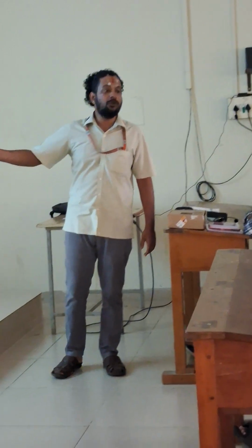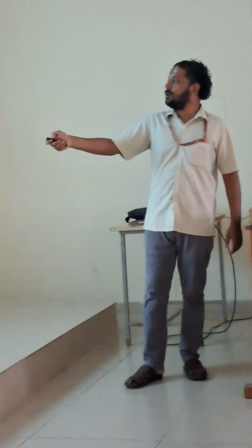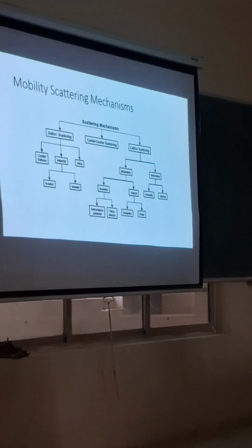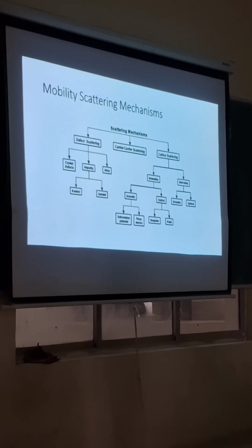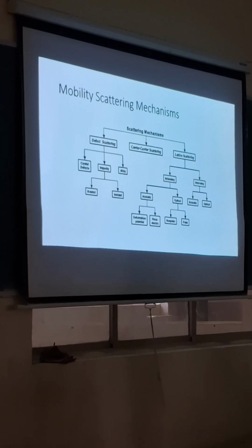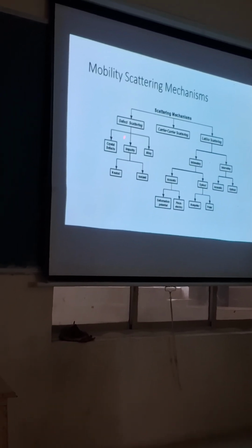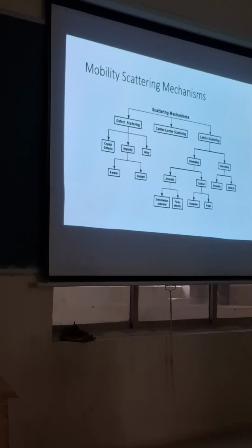And then we have the diffusion process. Higher concentration here, lower concentration here. Balance. So these are the equations for the diffusion process. And these are the different scattering mechanisms that we need to account for. We have the defect scattering, where I have a crystal structure, and the structure is not completely periodic. It has a defect, and those defects have their effects. So we have crystal defects, impurities, and others. Impurities can be ionized or neutral.